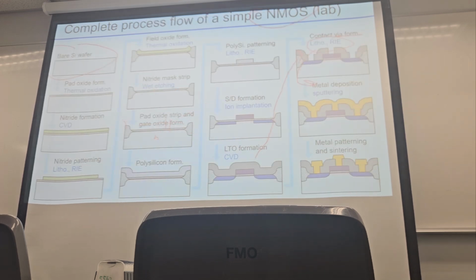Okay, so let me repeat again. The Schottky diode fabrication process is compatible with NMOS and CMOS. Right? So the only difference is that we need to create the region for the N-well and the N-plus doping. So then, how to do that? We can add an extra step.